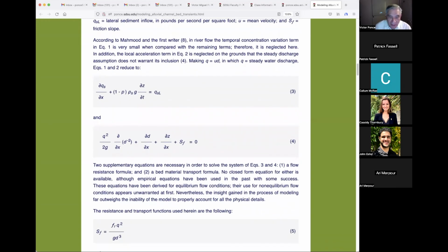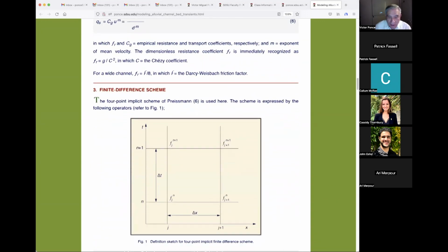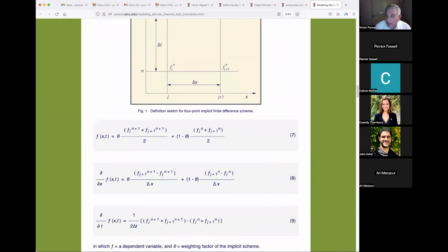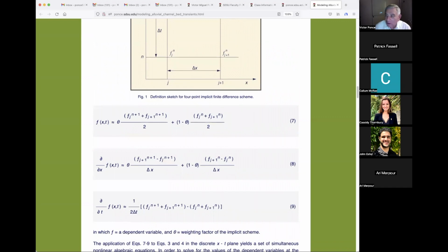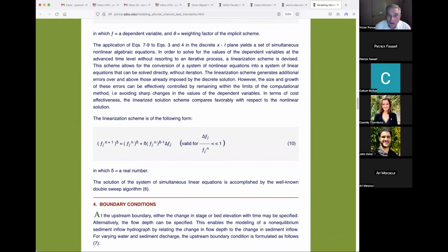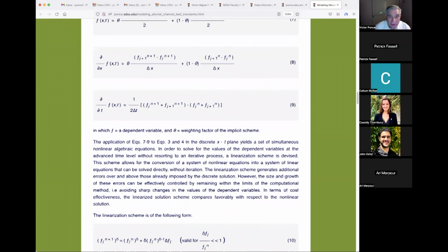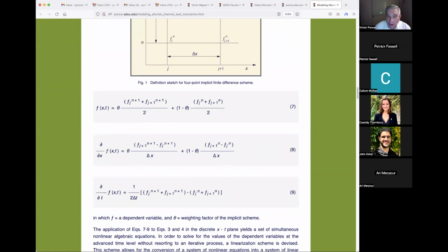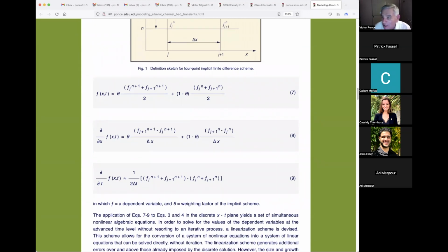Okay, so we did the calculation, and we used finite differences, which we're very good at. We used the Preissmann scheme, which is this over here. Those of you that took computational hydraulics already heard me talk about the Preissmann scheme, very well known. Due to Preissmann, a French engineer who developed the scheme at the time, 1961, and he became very famous because it was a very workable scheme. And it was based on this magic number, which we call theta, which is a weighting factor. I'm not getting there right now because if I get in there I can't get out in an hour. But the point is that without that theta, the system wouldn't work.